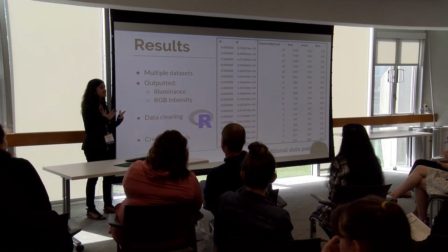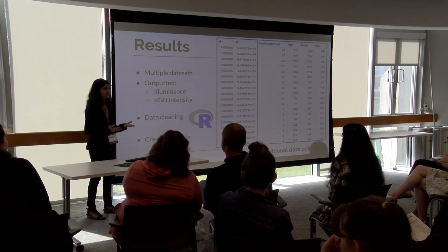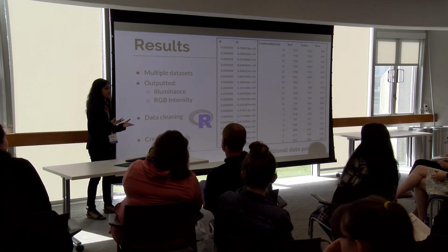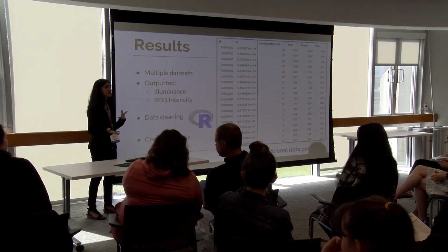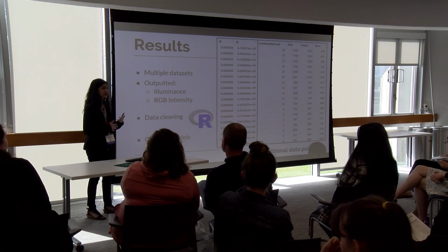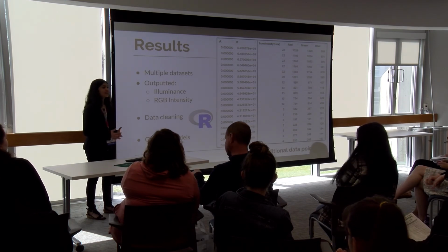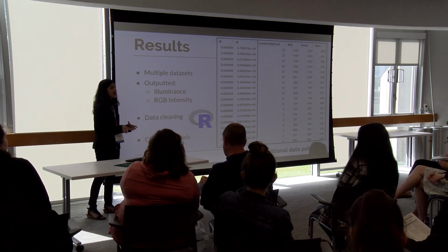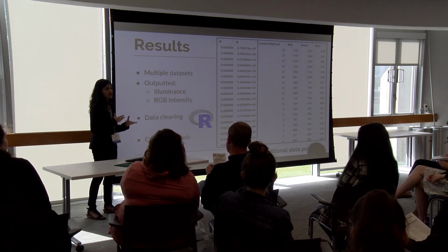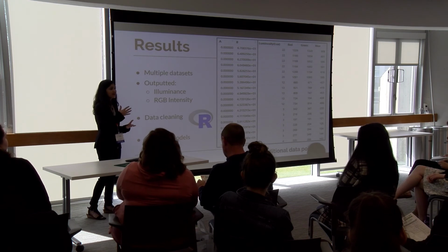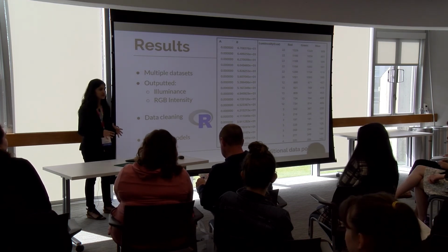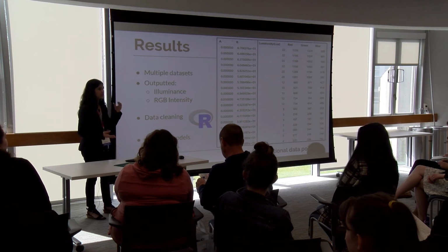Since lighting is subjective, some people prefer brighter environments and some people prefer dimmer environments. However, scientists have done a lot of research regarding this, the light science, and it depends on which type of room you're in. For example, if you are a doctor in a surgery room, you need a lux level of 5,000. But if you're in a dark area where you don't need as much light, then the lux level is a lot lower.